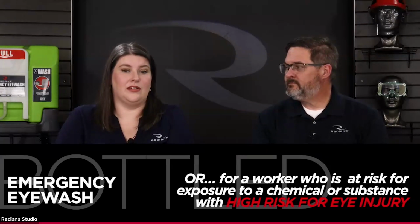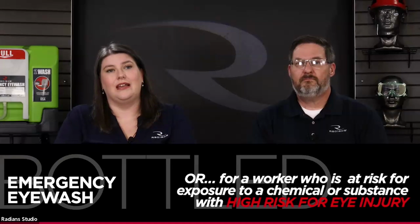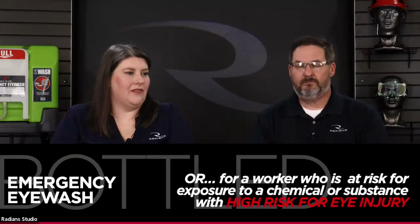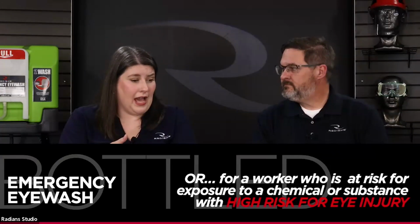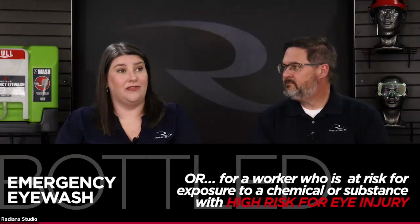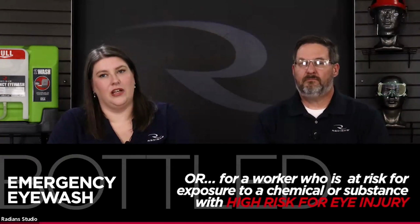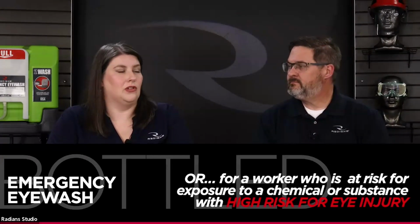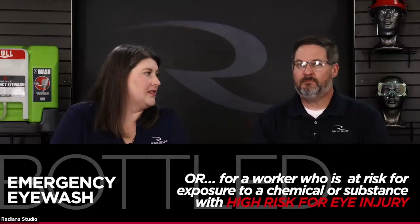If you have a worker who's in their workstation using this chemical that has the potential to be exposed, giving them a personal bottle that's at arm's length means that if they are exposed, they can grab that bottle, pop the cap, begin flushing their eyes, and then make their way, 55 feet or 10 seconds away, to the full station for the 15 minutes of flushing. In that scenario, you're really offering immediate relief and minimizing the damage that could happen to that person's eye.